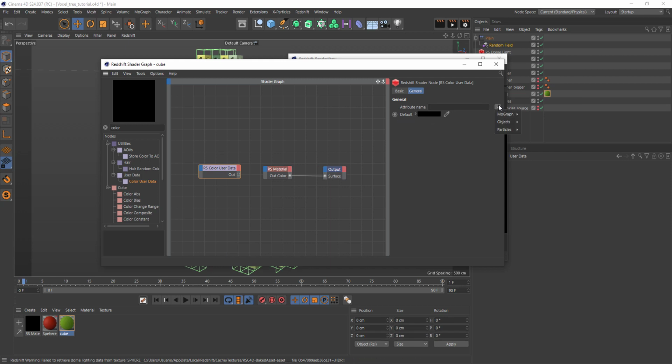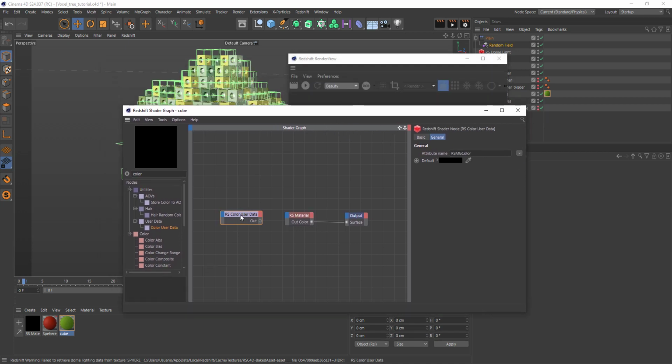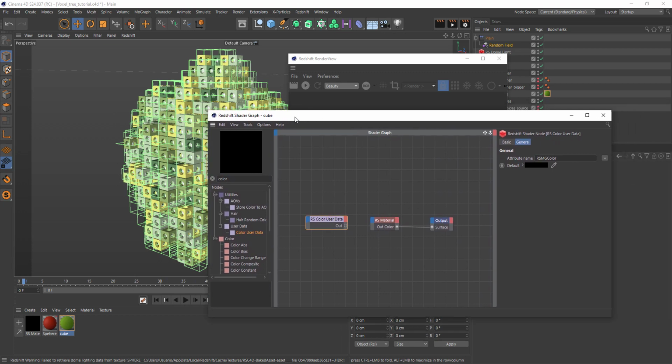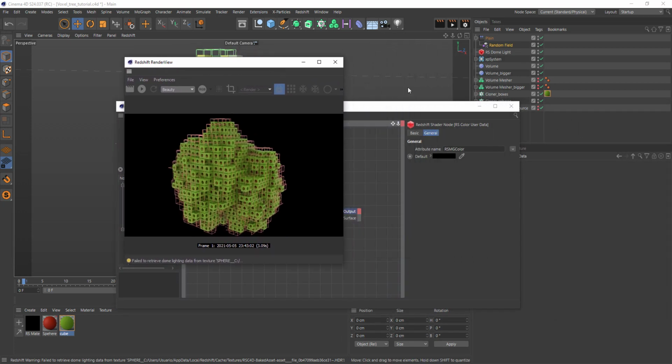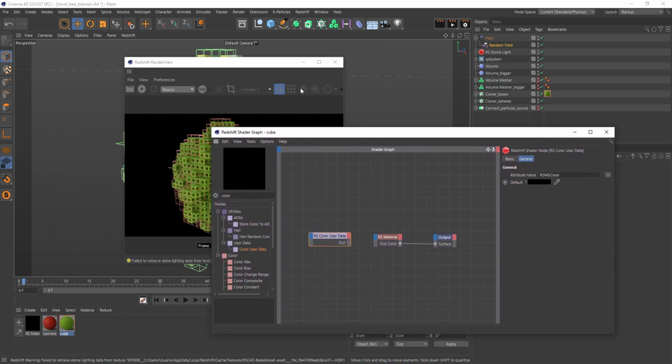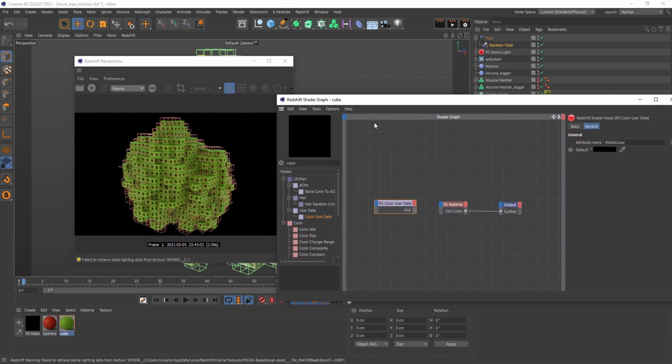In this case, we're going to use mograph information, the color of the mograph information, right? And this is going to read the plane effector information, because you have the material applied to the cloner. So this is going to be automatically read by the Redshift material.